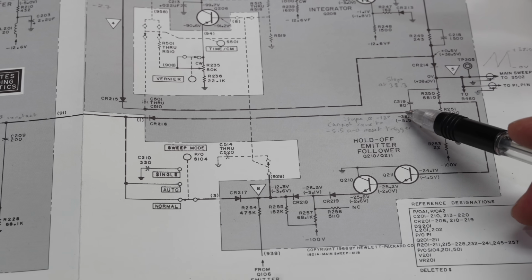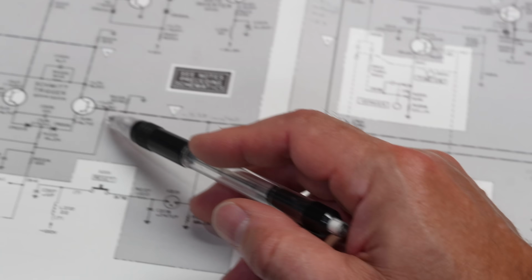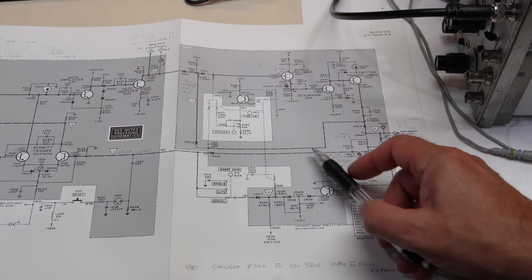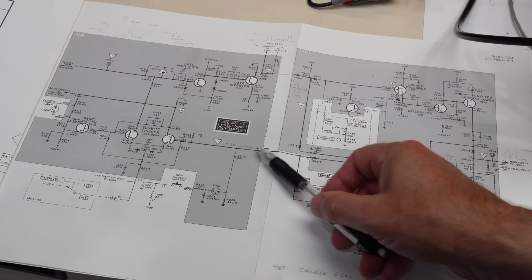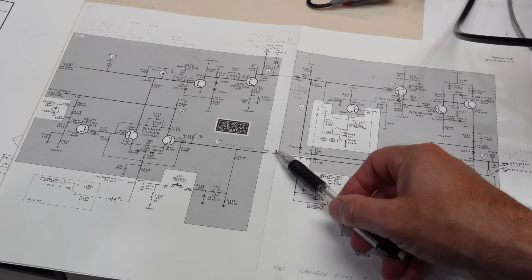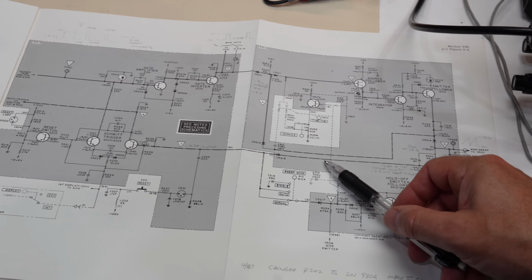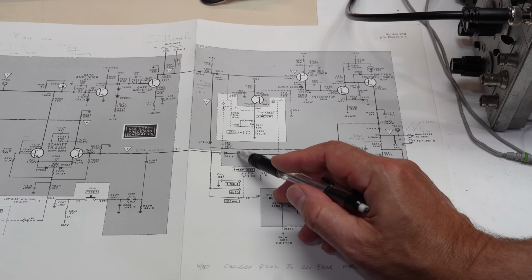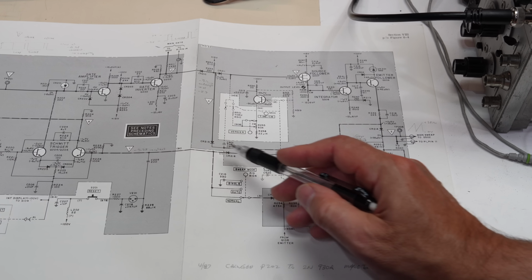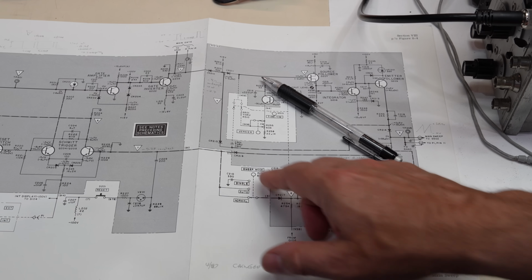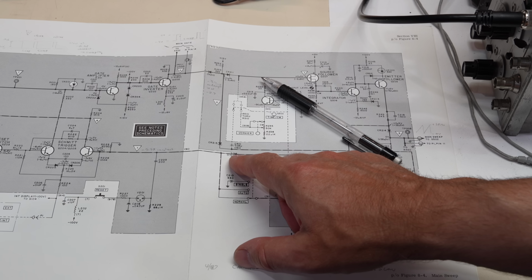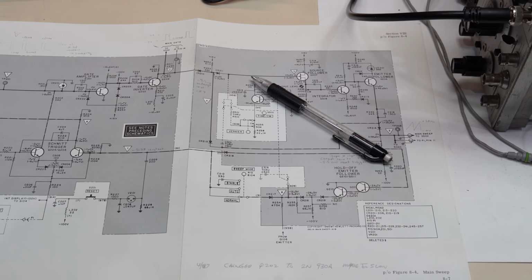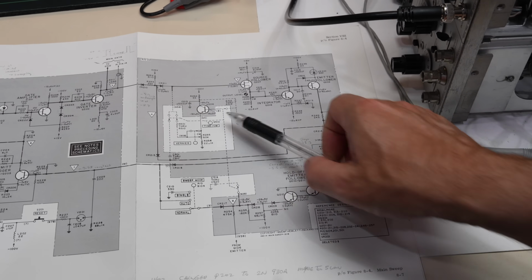That never goes to minus 5.5, so that never goes here, and that never resets this trigger. Something is holding it down. Something is holding that line at minus 12 or something. I'll just desolder this and see if this returns it to normal. If that is, then the fault is in this line and it's being clamped by that diode. Okay, let me desolder this and see if we get our level back to normal.